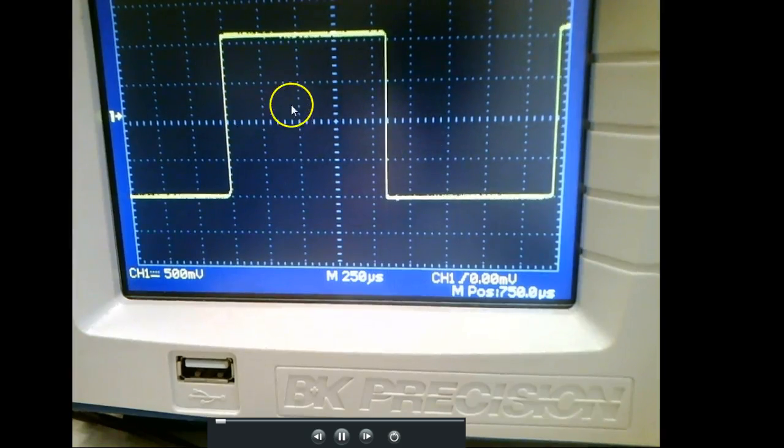Okay, so I go 1, 2, 3, 4, 5, 6, 7, 8. 0.2, 0.4, 0.6, 0.8. 8.8. Then I take that. I haven't even looked down here yet, because this tells me the time per big division, right? So I count the number of divisions, and I use 0.2 for each minor division. I take my number of divisions, multiply it by that, and that gives me the time.